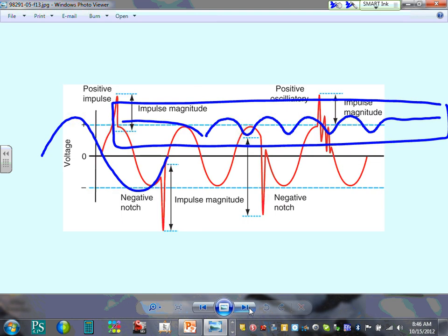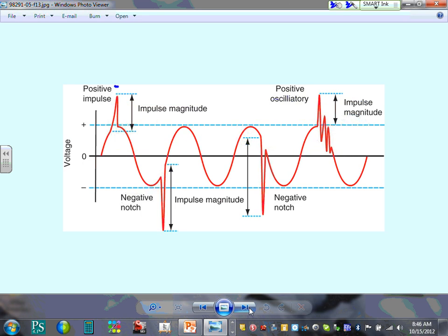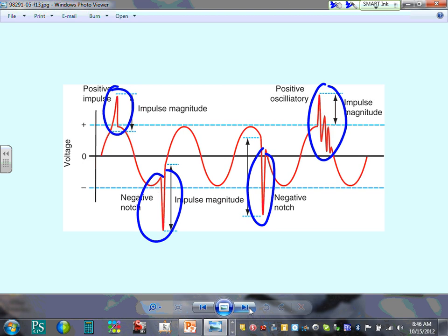Here are the spikes that could burn your equipment. I thought that's a really nice picture. These are the ones that kill your computers, for all these different reasons. See that? Chad was talking about all these spikes. If you have a motor, they don't affect motors that much, but they affect computers and electronic equipment a lot. They burn them. Surges, they call them surges. That's why your equipment at home is plugged into a surge protector device to get rid of all these. Shunt them, cut them off, zip them to the ground, tie them to the ground. Can I have thumbs up, Chad? Okay, cool. So having an isolated ground receptacle will minimize this.